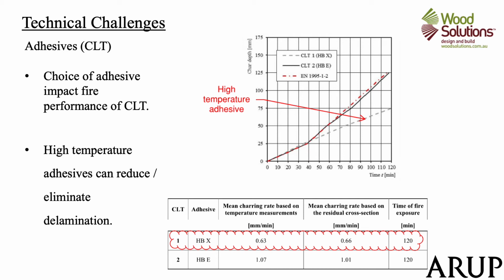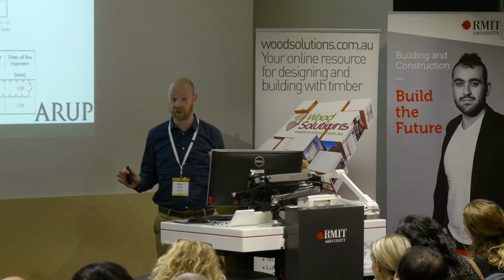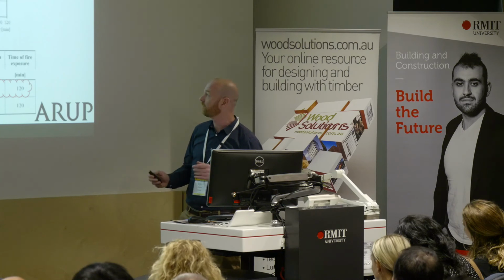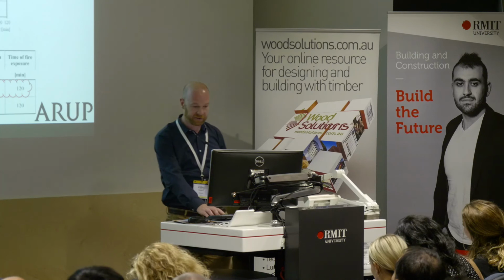To illustrate that, this is an excerpt from a paper from ETH in Switzerland, who are world leaders in timber fire research. They tested 2 CLT samples, both with PUR glue, so not even the formaldehyde glue, but this was a high temperature adhesive, and you can see the char rate through the high temperature adhesive basically behaved like a solid block of timber, so very predictable, very fire resistant, whereas it wasn't so good with the standard glue.